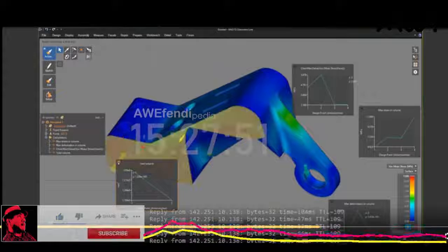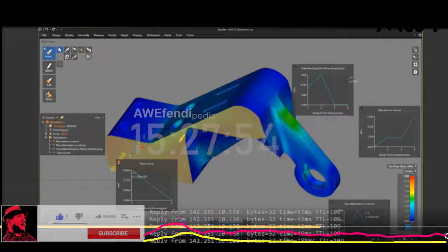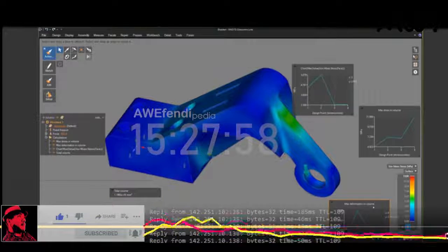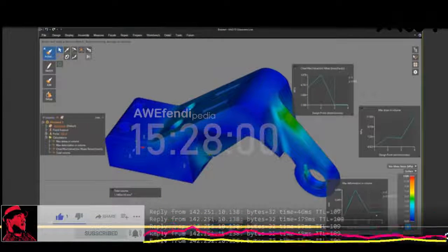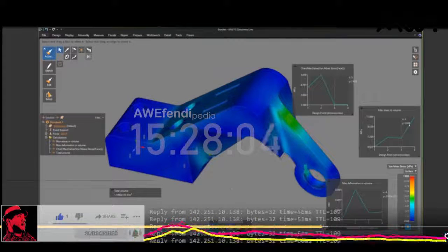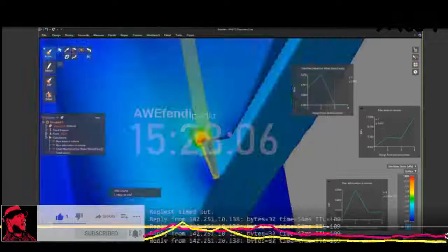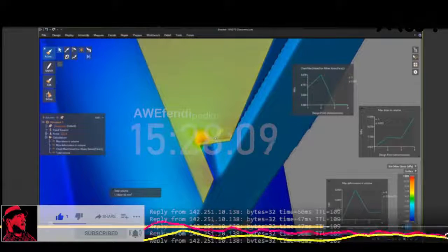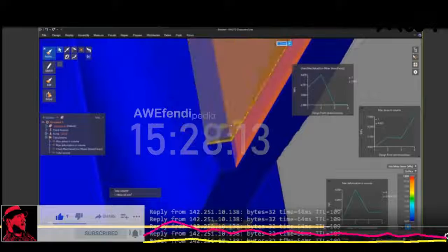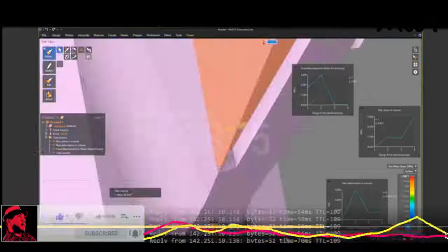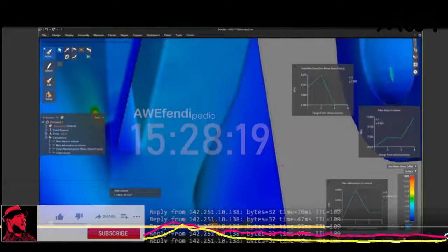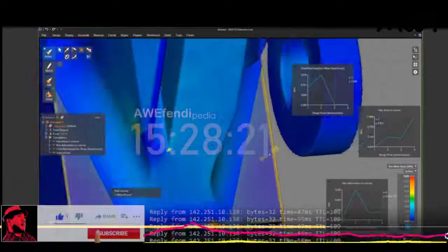I shaved down a little bit of the weight, maybe offset by adding that extra material. It looks like deformation is stable here, which is great. I added a little bit more stress, and I think what it's doing is looking at this little sharp point here. So I can go in and think about this differently, maybe change the location of some of these slots, give myself some more meat back right there, so I don't have that sharp area, and hopefully that artificial stress goes away.